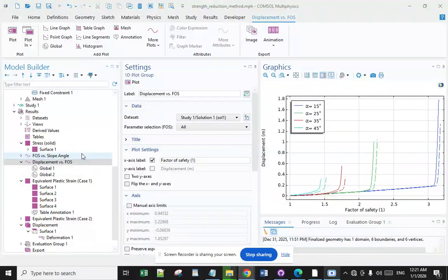A conventional single coefficient strength reduction method is widely applied in slope stability analysis, but this method ignores the attenuation degree of different parameters in slope destabilization. A new double strength reduction method considering the different contributions of mechanical parameters is proposed in this study, and simulation is used for evaluating the stability of non-homogeneous slopes.